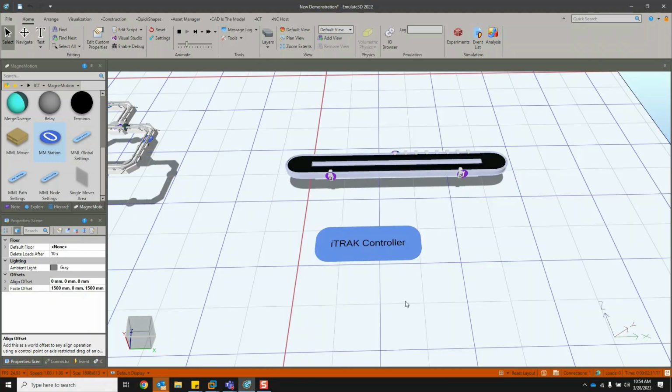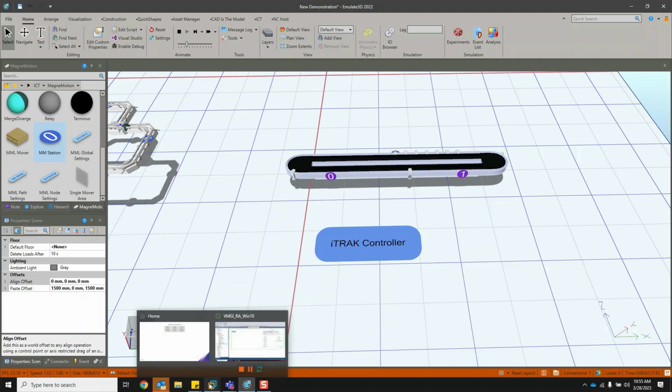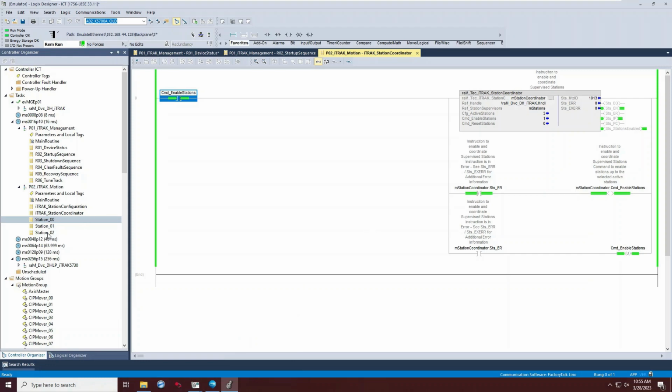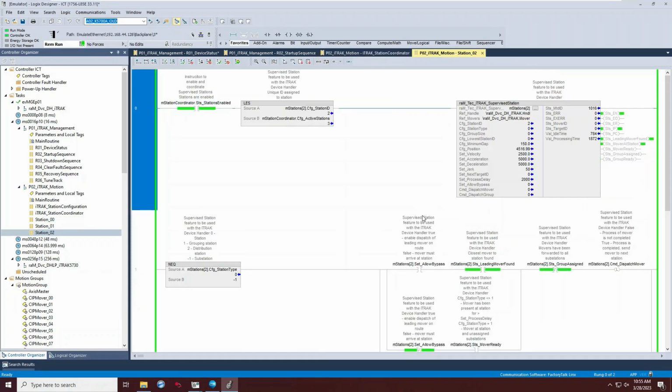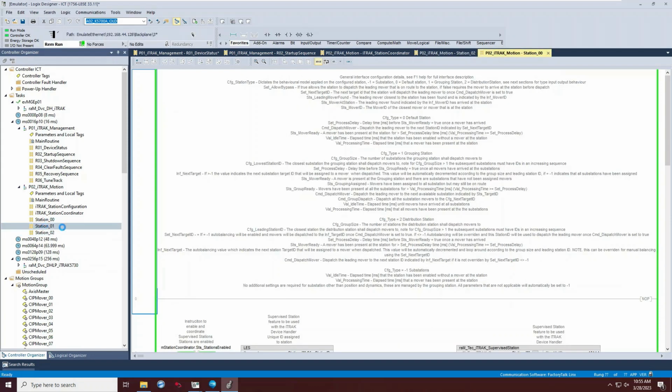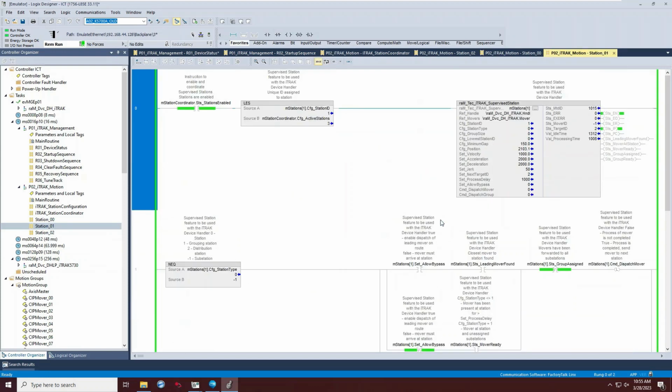So in addition to the I/O browser, we can also prove out that this is really reading off of the controller by changing some of the values at the station. So let's, for example, say, let's change the speed from 0 to 1, or the speed that it leaves station 0 with. So we can come into here, we can come to the different station points, and we can change what we want our speeds to be. So I can see station 2, station 0, and station 1, and I can see what each of those values are. So right now, it arrives at station 2.